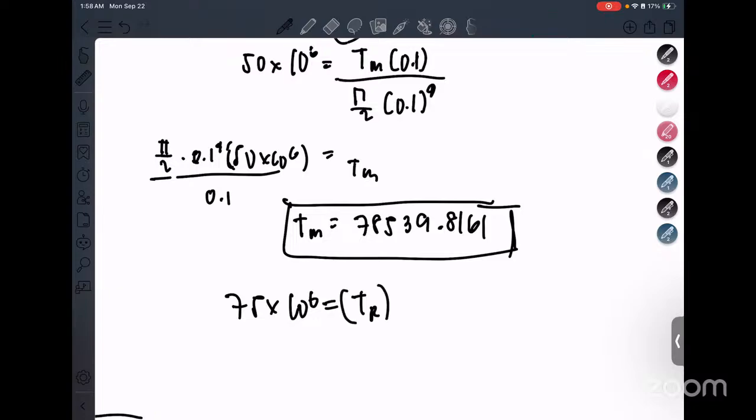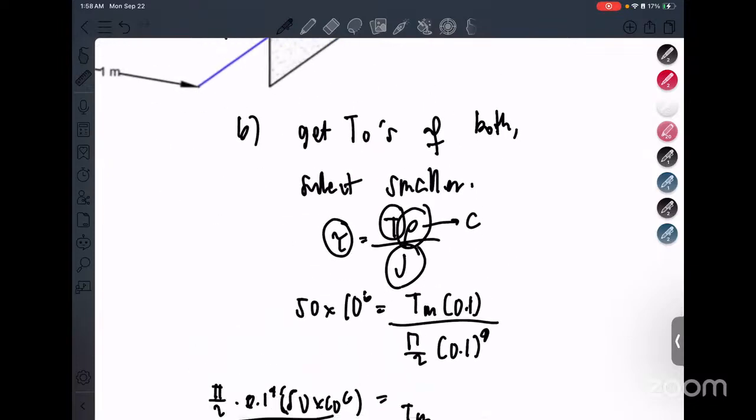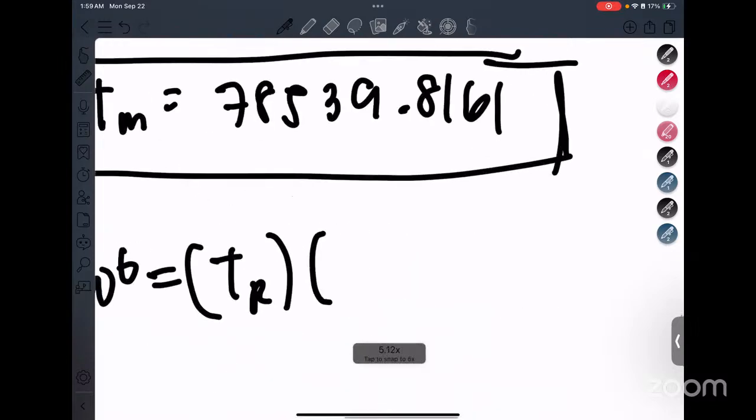Yeah. So this is the force. Again, that is the torsion times rho, which is the subradius or the radius of the section. Because again, yung shear stress is proportional, like the farther out you go or the larger your rho is, the larger it is. Linear relationship. Since we're getting the maximum case, we'll just get the largest possible value for rho, which is the radius, over polar moment of inertia.